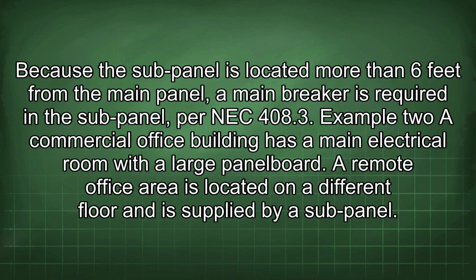Because the sub-panel is located more than 6 feet from the main panel, a main breaker is required in the sub-panel per NEC 408.3.